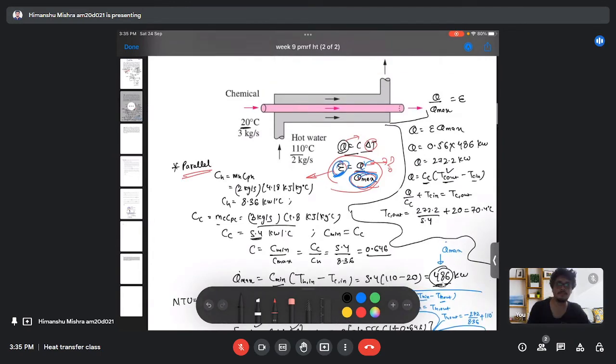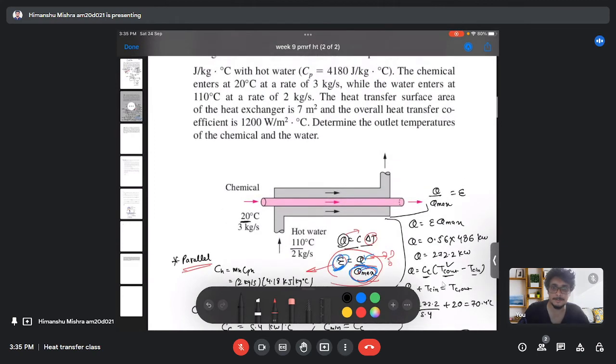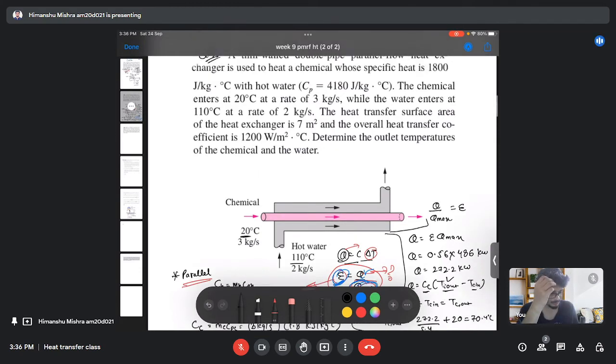So in this question we have given the parallel flow heat exchanger. We have given the two inlet temperatures of the fluids, one for the inlet temperature of the hot fluid and the inlet temperature of the cold fluid. We have given the heat capacity, specific heat rate and the overall heat transfer coefficient as well. So we need to find the outlet temperature. For the outlet temperature, we can use the standard heat transfer relation, which is the difference of the temperature of the fluid at the inlet and outlet. So for that, we need to find the heat transfer itself.